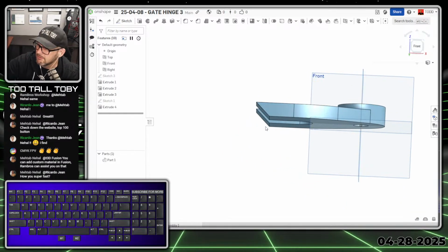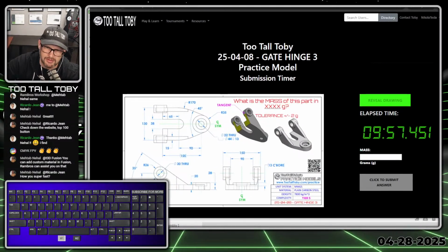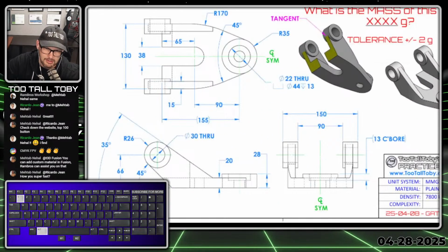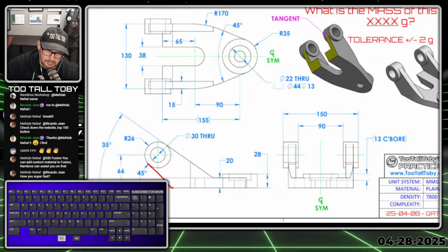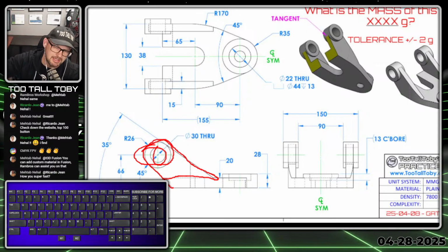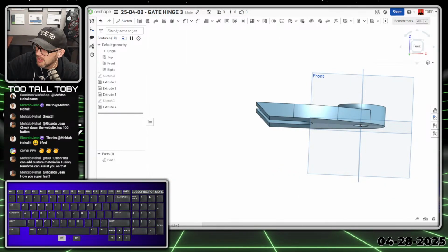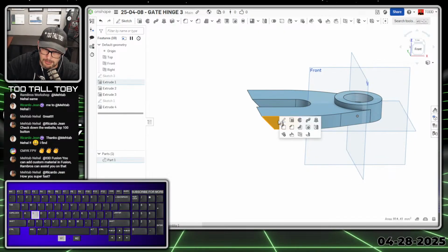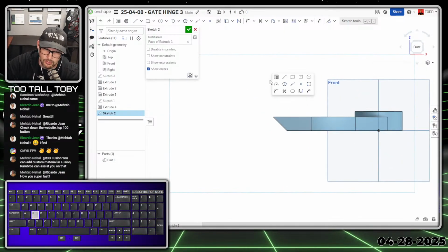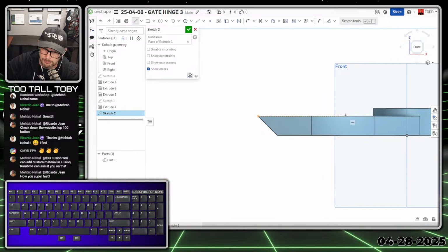And so now we can begin getting into what is going to be kind of the end game of this model, this blade section over here. So we can create a collinear line, a line here at an angle, create this shape, create this circle, and then we should be able just to continue to do those extrudes like we did earlier. So what we can do here is we can go to this face here, S key, begin a sketch, N key to get normal to, S key to begin a line. Could maybe start our line here at this point, or maybe even over here. Come over here to this point, just create like a quick line running along the bottom.